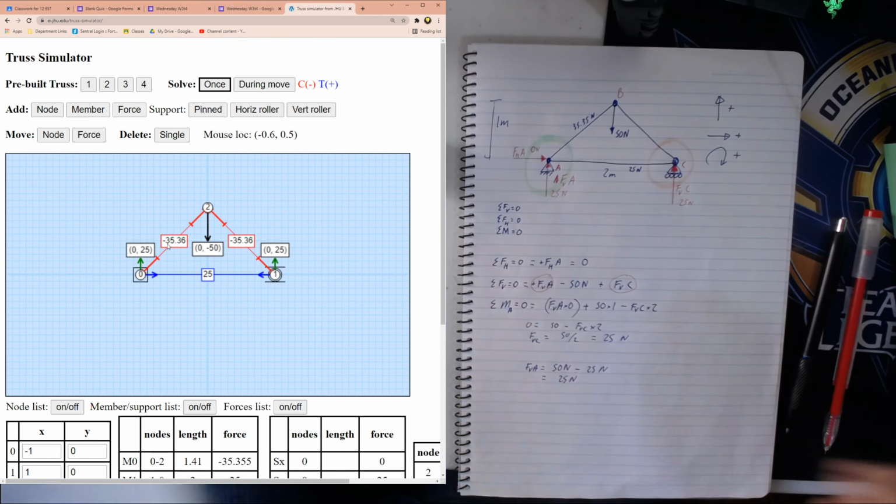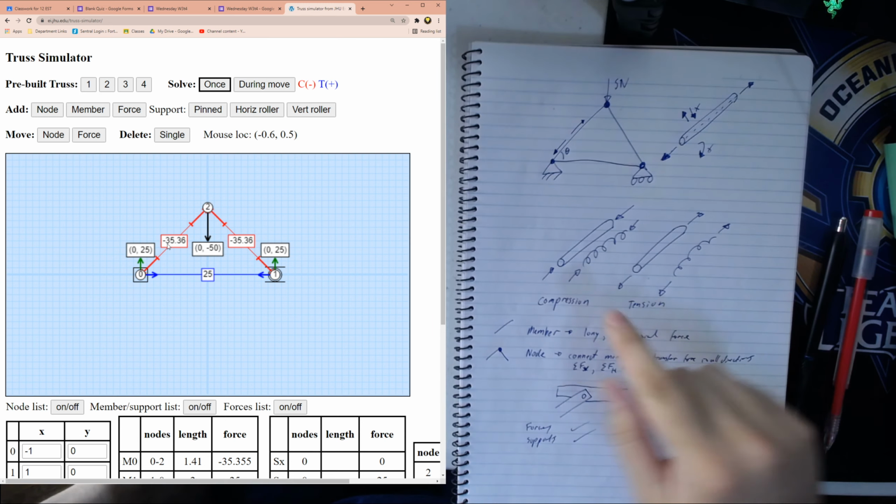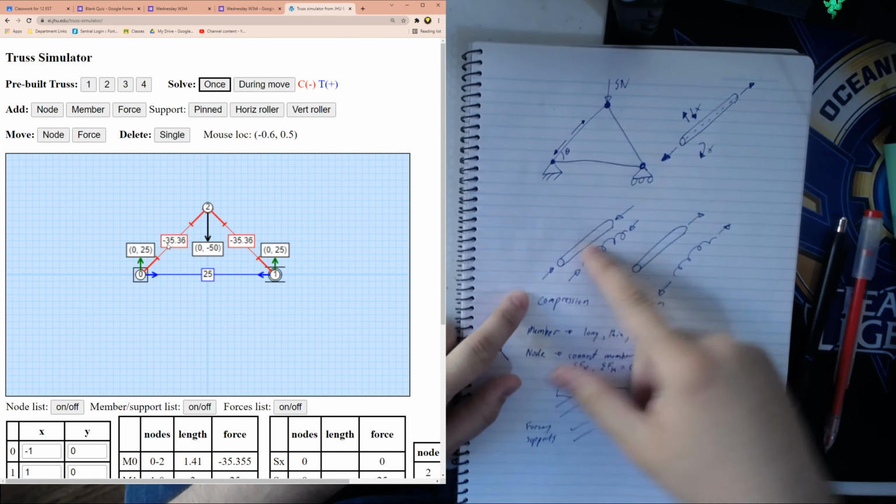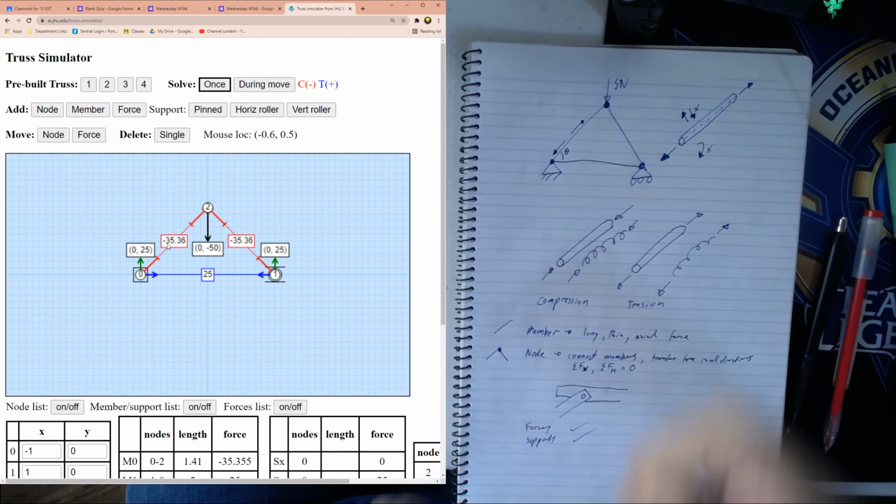What they're referring to over here is like our example. Let's ignore that ours isn't 5 newtons. We have a term called tension or compression. This is referring to the force that the member is experiencing. If a member has the force going into the member from both sides, so you're pushing the member, like squashing a Coke can or pushing a spring in, that is under compression.